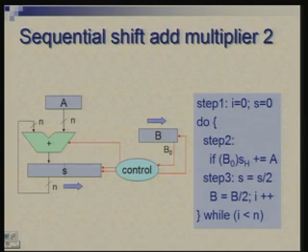So, it is the partial product which you have accumulated that keeps on shifting right, instead of shifting A to left in every cycle. We are shifting the partial product obtained so far to right, which actually maintains the same relative position and achieves the same effect. And the consequence of that is that adder needs to be only an n bit adder.